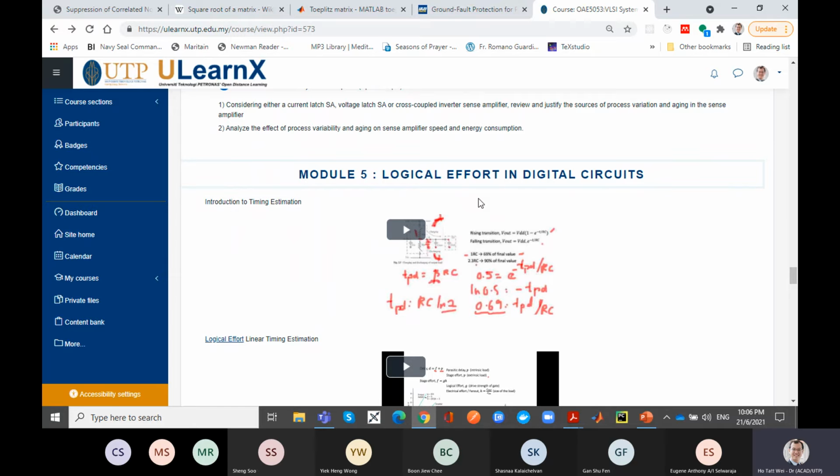your life, you know, if you take digital electronics at the undergraduate level, I think most of the lecturers, if they're a little bit sloppy, will tell you that the number of stages equals the propagation delay. You get more stages, you get more propagation delay. And then suddenly you come across logical effort and someone actually tells you, no, actually sometimes you can have more stages and it can actually make your chip go faster.